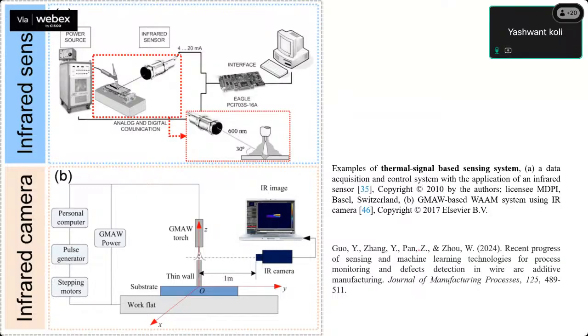Temperature sensors include pyrometers and fiber Bragg grating sensors, FBGs. Pyrometers are very low cost sensors to monitor melt pool and vapor fume temperatures, useful for detecting incomplete penetration and burn throughs, but limited in defect coverage. So these are very cheap sensors, the pyrometers.